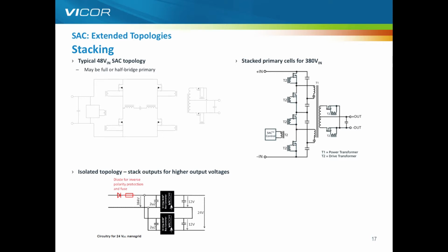One of the other things about this stacking, and also part of the zero voltage switching, zero current switching techniques, is that we can use, for example, stacked 250 volt MOSFETs on the primary side of our 380 volt input units. And as the resistance of a MOSFET, the RDS on, is related to the difference in voltage to the power 2.5, if we go from, say, using a 600 volt FET in a hard switch topology to the 250 volt FET in this stacked zero voltage topology, we are, trying to do this in my head, maybe 9 times lower in RDS on. So we can have a huge saving. Also, the QGD usually follows in the same way. So using higher performance MOSFETs, we have that higher efficiency, higher switching frequency, and that positive spiral. So that's stacking the inputs.